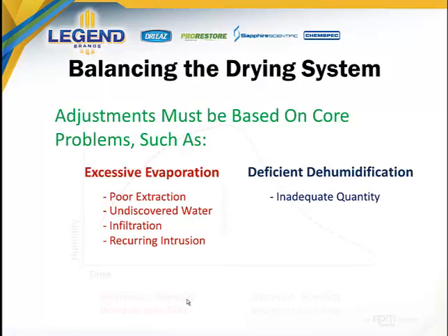Ensure that you properly calculated for your cubic meters. Ensure you've properly described the scope of damp. And then at the end, as an end result rather, ensure you've selected the appropriate factor and done the appropriate math to size dehumidification. If you've done this math properly, this should not be the reason for your high humidity within the space. Secondarily, inspect the dehumidifier itself and ensure it doesn't have any major mechanical problems.